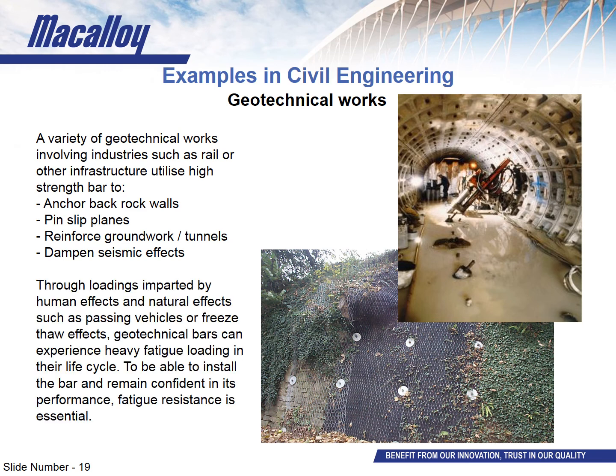Various phenomena such as vibrations or thermal changes can subtly alter the loads these bars experience. Independently, each of them wouldn't give the system too much trouble, however they seldom work alone. The combination of more than one of these conditions can accumulate cycles quickly, and if working simultaneously, they can result in larger stress ranges. Both of these worsen fatigue demands, so having a bar that resists fatigue in such a manner is very important to reduce the risk of failures and negate the need to replace any bars before their intended service life has elapsed.